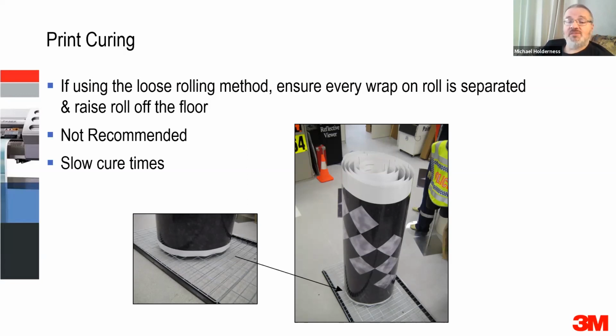I've also seen guys put fans into them. So they use something like a little computer fan in the bottom just to suck the air out the bottom. Make sure that the fan is sucking down and not pushing up. If you're trying to push air up into it, it's not going to cure very well because the solvent being heavier than air is going to want to drop down.